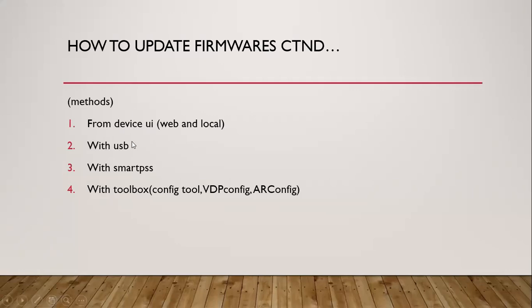Alternatively, there are some files that you download from the site that have a lot of files, like about 10 files in a compressed folder. You will extract the files, plug in the USB, put it in the NVR or the DVR, power the device off, power it on, then the device will upgrade by itself. It will continue upgrading by itself.